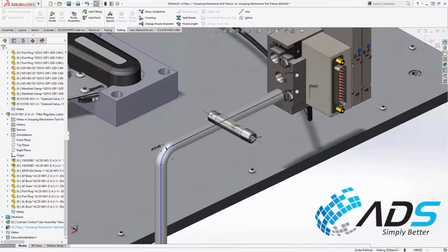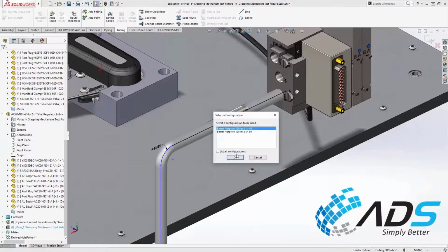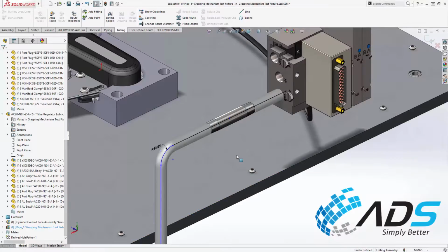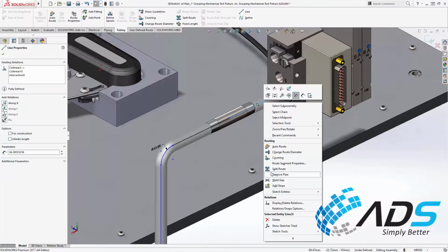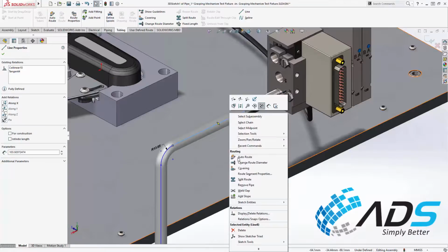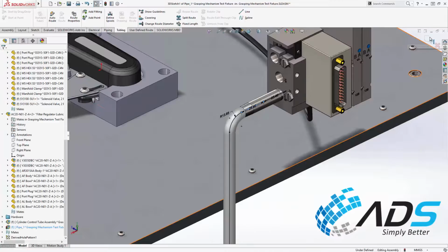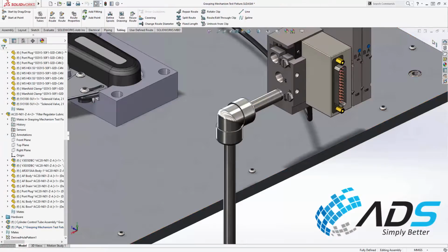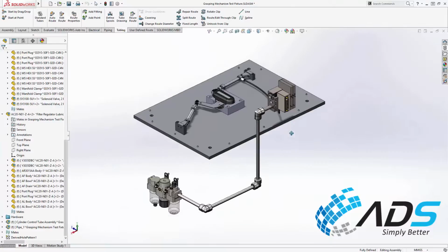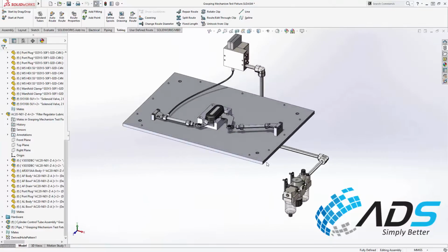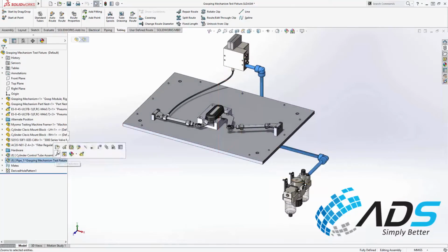To place a pipe nipple, simply drag it and drop it onto the route like any other route component. Routing splits the existing pipe at this point, like a T or other junction types. For this nipple, however, we no longer need the adjacent pipe segments, so we will remove those segments with Remove Pipe from the right mouse menu. Notice that the nipple now acts as a low-cost pipe segment on its own, eliminating the need for a custom fabricated pipe in this instance.